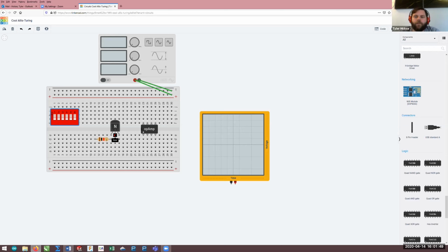You can't have a gain of 100 when you only have a 1 volt signal and your op amp only goes to plus or minus 15 volts. So the important part for circuits is not always that the students get the circuit, it's that they know the limitations, and there has to be ample value in letting them mess up.